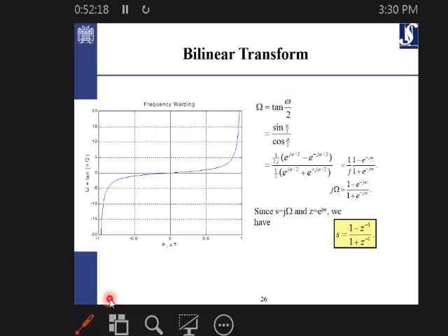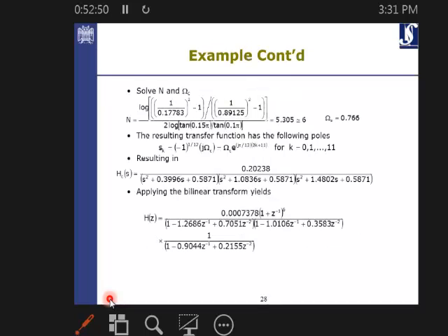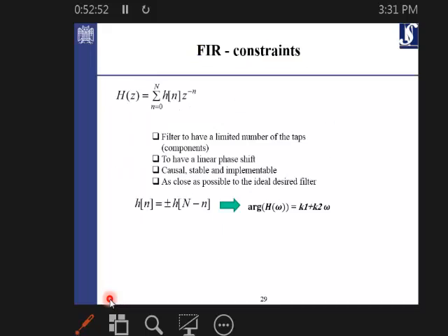If you have such a strategy to design a filter with different levels, it's not smooth like, for example, the first method, which is something like that, or for example, the high pass filter. So if you have something which is frequency selective with different levels, you can use this bilinear transform. And this is an example, the same example we had already, just by replacement of s with the new bilinear transform, you will get a new filter.